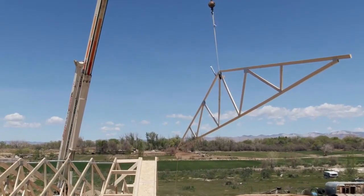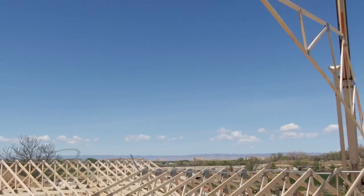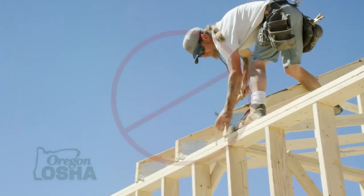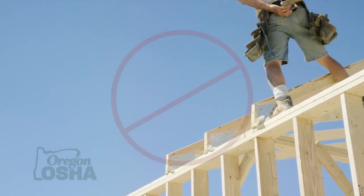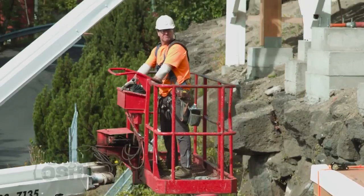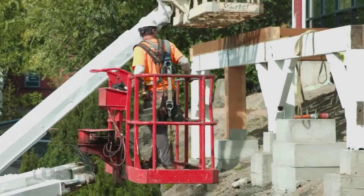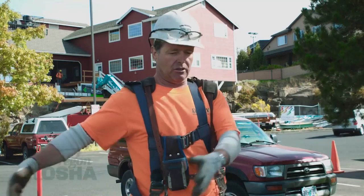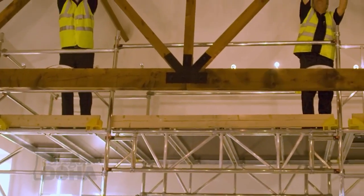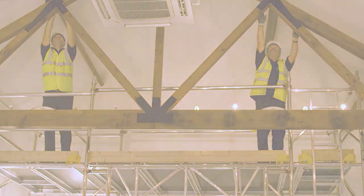A lot of our jobs, crane, just fly one truss at a time, but that's big trusses. There's a lot of different ways of doing it. We used to always walk the top plates and roll the trusses and bend down and put the blocks in. Now we work off of scissor lifts, man lifts, whatever, and the guy's near plate height, but the plate is actually mid-chest or stomach because he's on a scissor lift, and you can roll the trusses that way. And you have a nice platform to have all your blocks. Or you could build scaffolding, but scaffolding has its own inherent pitfalls too, because you got to build it right.